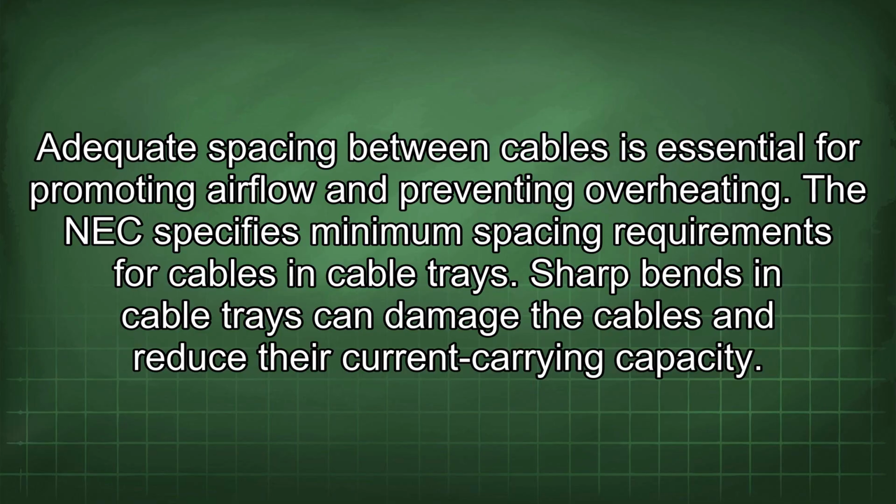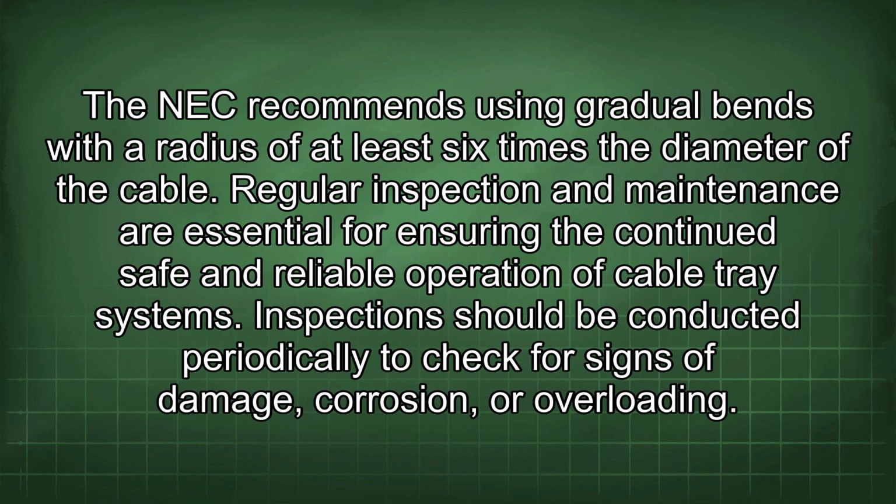Sharp bends in cable trays can damage the cables and reduce their current carrying capacity. The NEC recommends using gradual bends with a radius of at least 6 times the diameter of the cable.